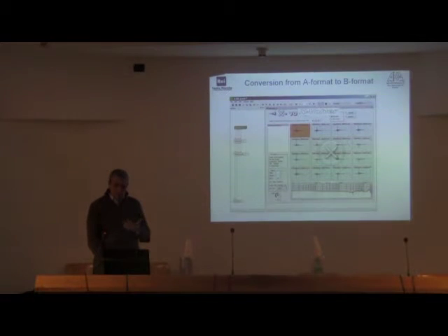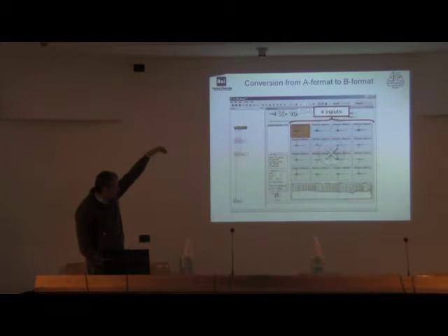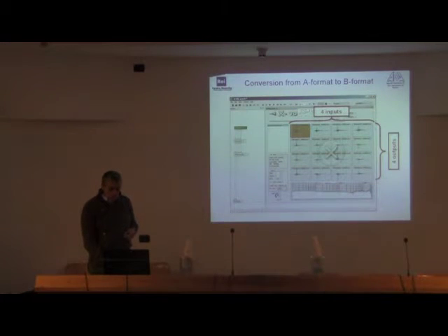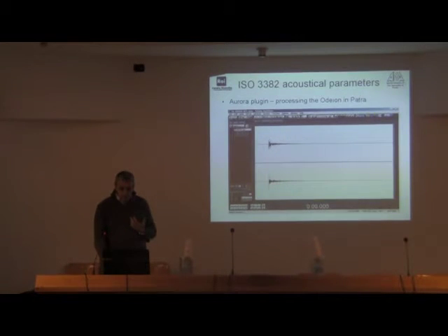You load a matrix of FIR filters, and it does the convolution. In this case, the plugin is working with 4 inputs, which enter the matrix from above, and the result of the convolution comes out horizontally on the right. So every output is the sum of the convolutions of the 4 capsule signals multiplied by the proper FIR filters.